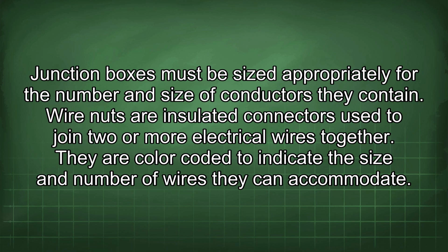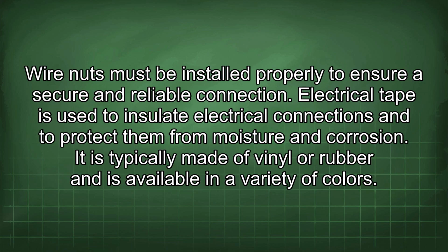Wire nuts are insulated connectors used to join 2 or more electrical wires together. They are color-coded to indicate the size and number of wires they can accommodate. Wire nuts must be installed properly to ensure a secure and reliable connection.